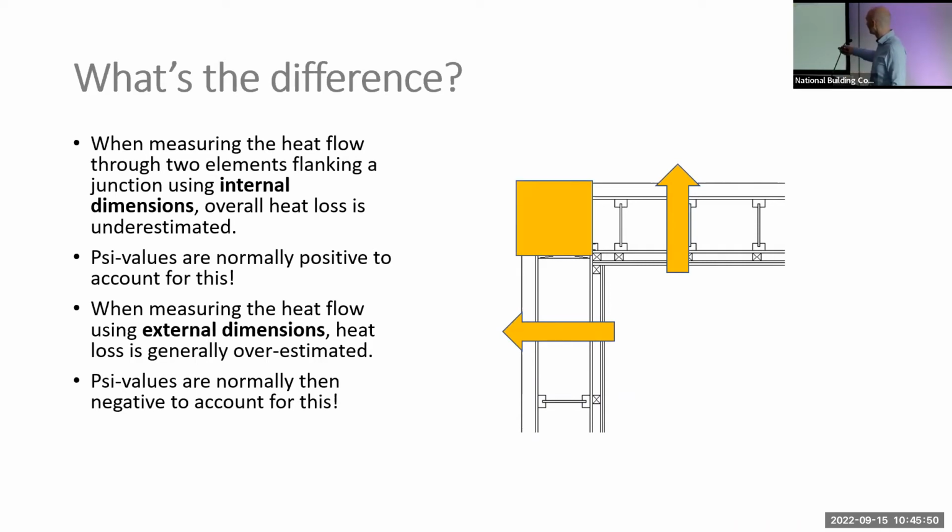If, on the other hand, we measure the building externally, so go back to the point on Passive House, we've measured that wall with the same U value, we've measured it out to that point there. Okay, so we put that entire area of wall into our area calculation in DEAP, and the same thing applies to this wall here. And now we've actually measured this corner twice.